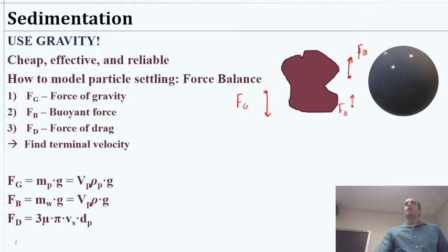There is a bit of a special case where we might do particle flotation instead of sedimentation. It typically requires aerating the system with very fine bubbles, letting all the particles stick to bubbles, and then letting all of those bubble-laden particles float to the surface, a kind of reverse sedimentation. It's essentially using the same principles, primarily the buoyant force instead. But mostly we'll look at this force balance where the force of gravity is dominant, or at least we hope so.